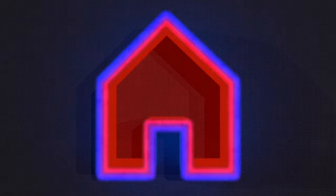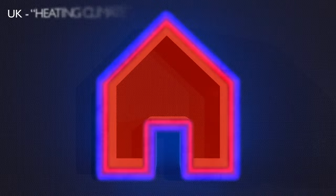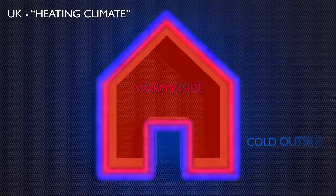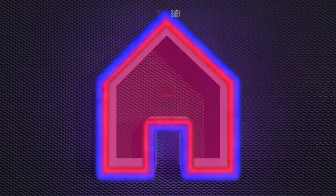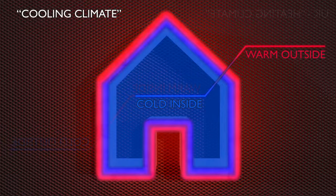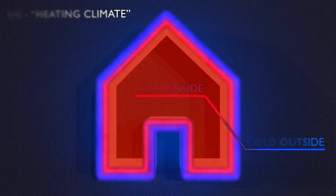Let's start with a look at the fundamental basics of moisture management in buildings. The primary driver of these interactions is the difference in temperature between the internal and external environments. The UK is described as a heating climate, which is to say the internal conditions are typically warmer than outside. As we move out through the building fabric, the temperature reduces. For buildings in cooling climates where air conditioning use is more typical than heating, for example in the Middle East, this is reversed. Today we'll focus on UK practice.